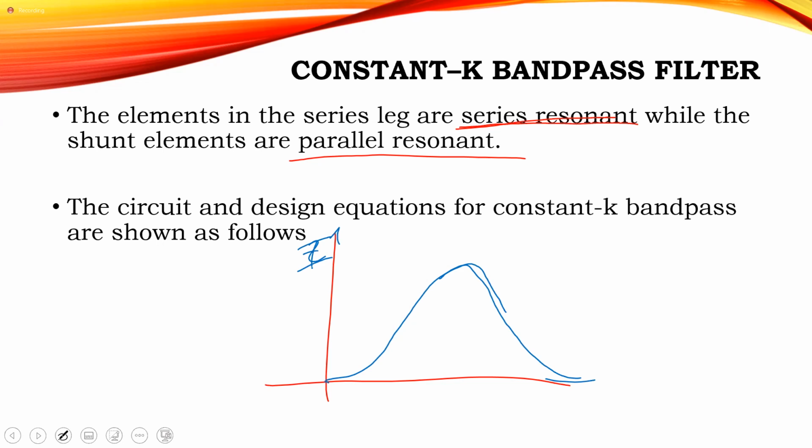Anyway, so this is the output in terms of your series circuit. You have maximum current at the resonant frequency, so you want maximum output. So this is at F0. And then at your cutoff frequencies, you have F1 and F2, all right? And that would give you your bandwidth.